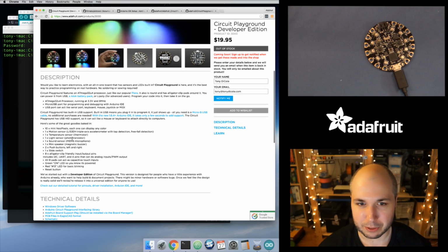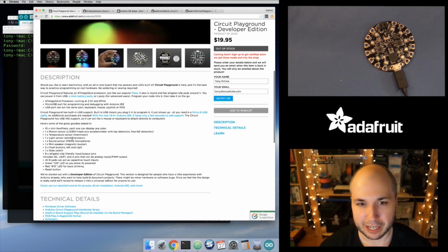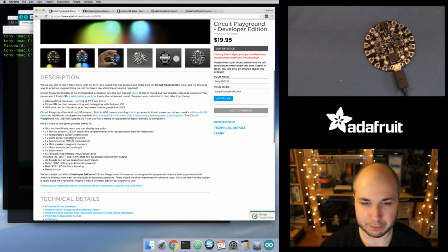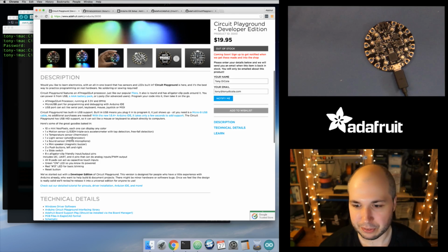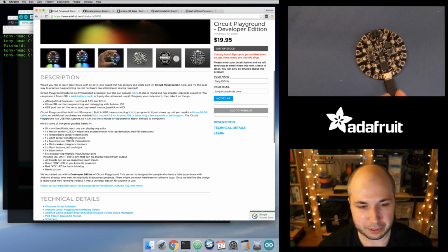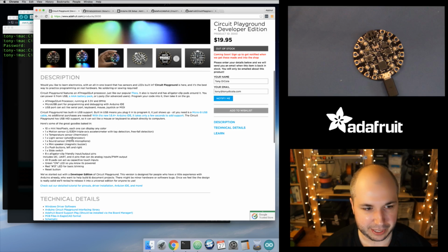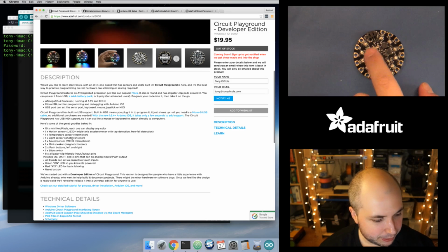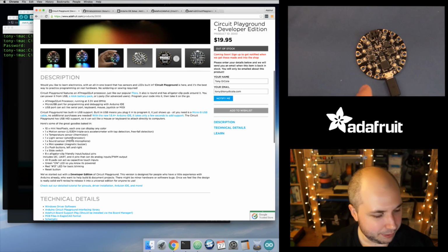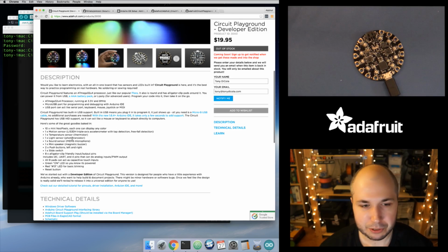That's fed into an analog input on the chip. And so just with an analog read call in the Arduino IDE, you can basically get a value that's dependent on temperature. So things can change. And then there's also a little microphone, so also another analog input on here. So you can detect sound pressure and things like that. A couple push buttons, so left and right push button right there. And then there's also a slide switch kind of in the middle here, so you can move that in between two different positions, like on and off.